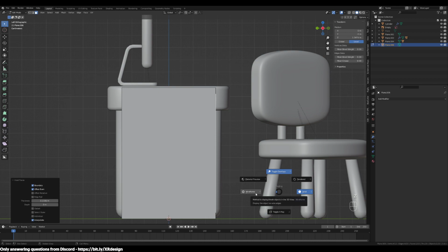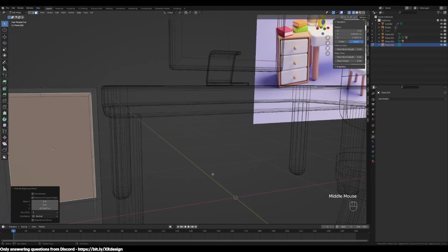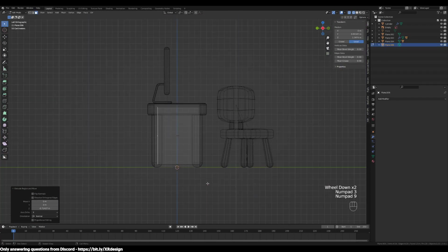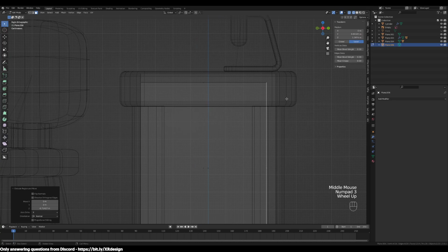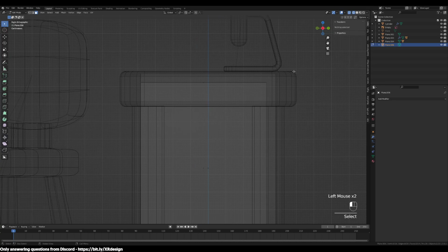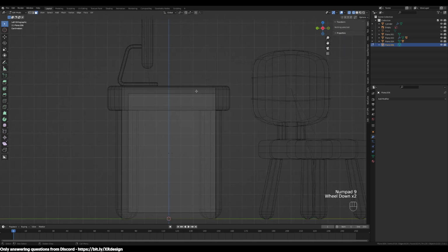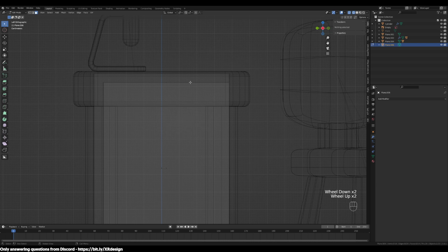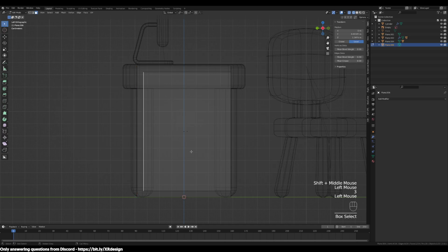So if you go to wireframe view and hit E, you'll be able to see how much that goes in. That was the purpose of orienting the camera to 3 and 9, to just flip that view. I'm seeing this as the front view, but obviously it's wireframe, so you could just go to side view and tweak it that way. You'll just have these desk objects in the way. So I prefer it to be on the other side, and it should be a little bit lighter so it's visible, but not too big of a difference.